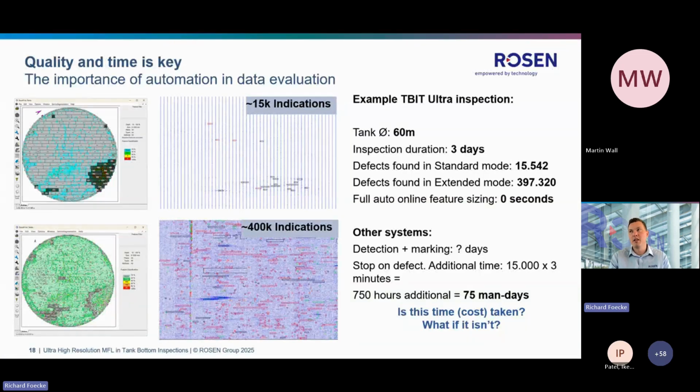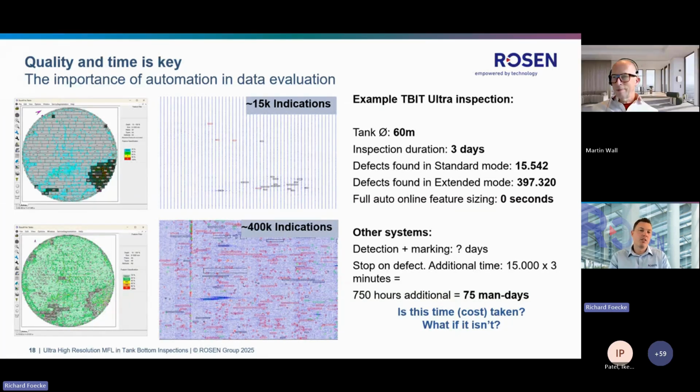With the tool itself, we can run through some water. The sensors and the drive units are all watertight, so that is no problem. However, if there were a completely flooded floor, we would of course not like to do this. This is defined in the cleanliness requirements. But in the end, moisture does not have a direct influence on the MFL and eddy current measurements. And if it's not too much, we can still do the inspections through small areas of water.